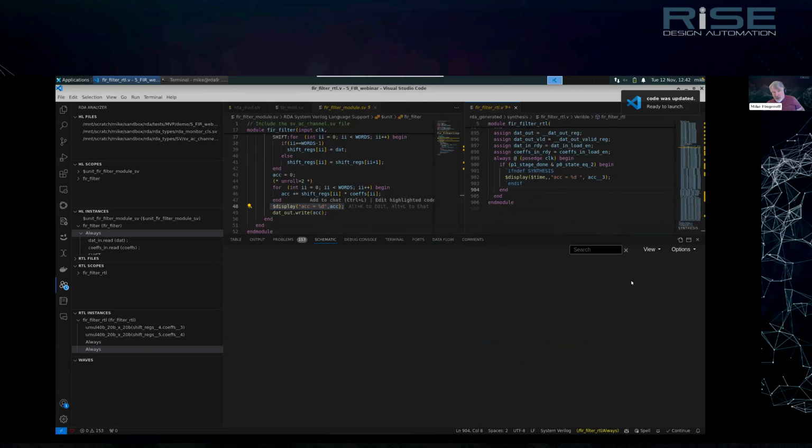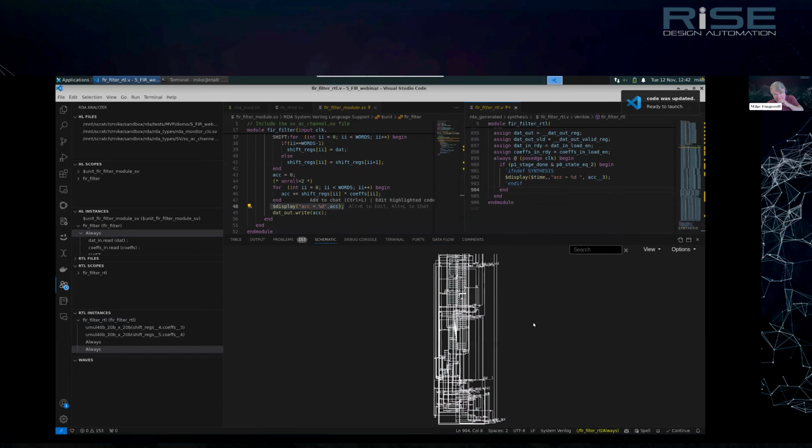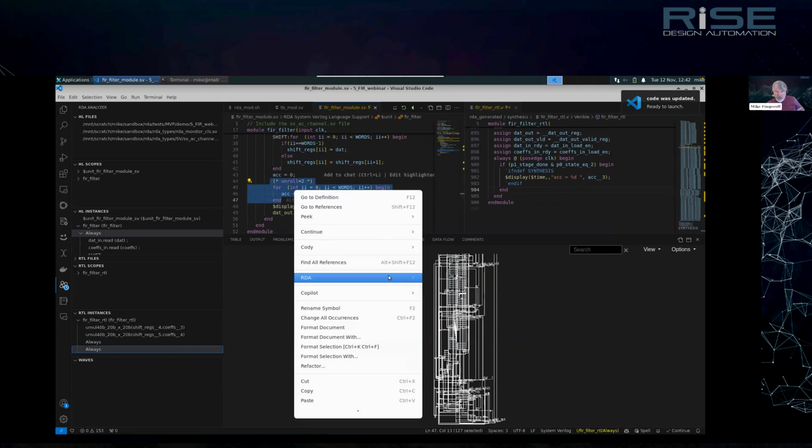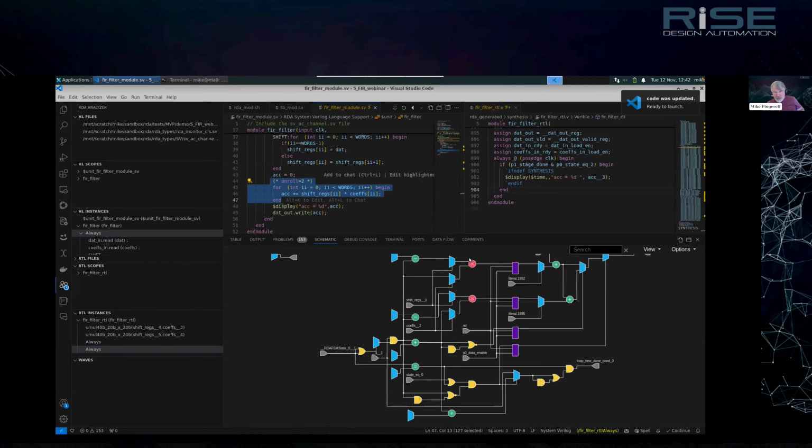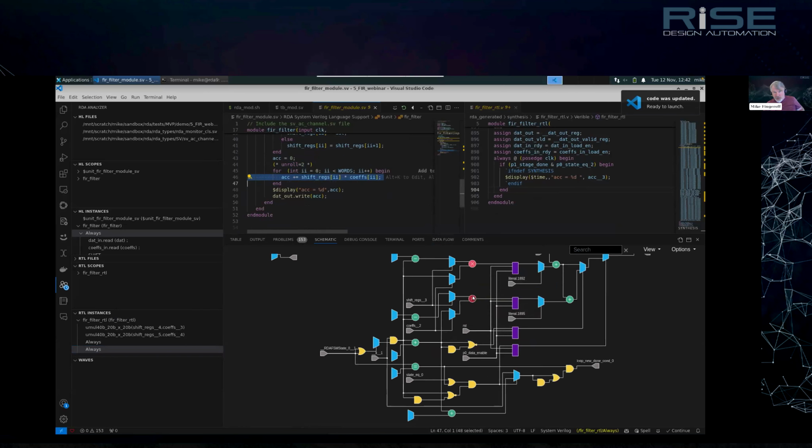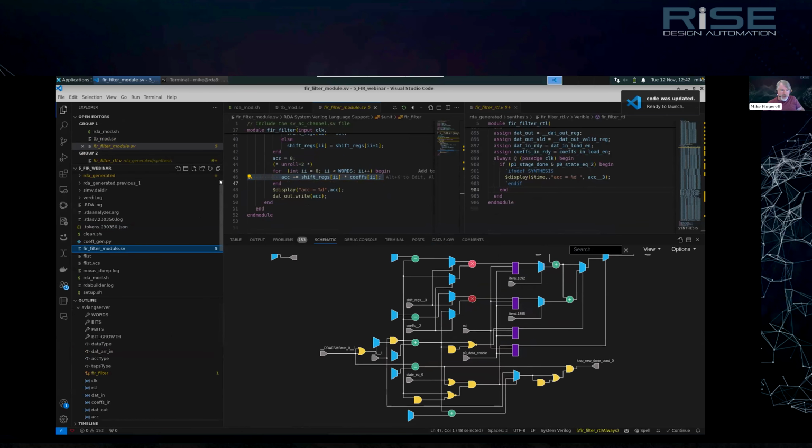This is the schedule IR, so this is very tightly coupled to the IR database. And again, this is why looking at things graphically can be complicated. It's kind of a sea of gates, but you do have the ability also to go in and say, show me just that section of the code. And sure enough, then these are my 2 multipliers from my unrolled loop feeding my mini adder tree and the FSM logic.